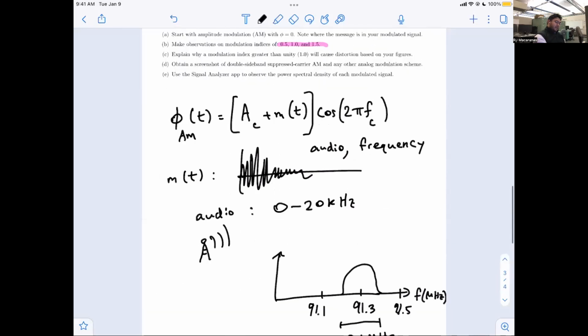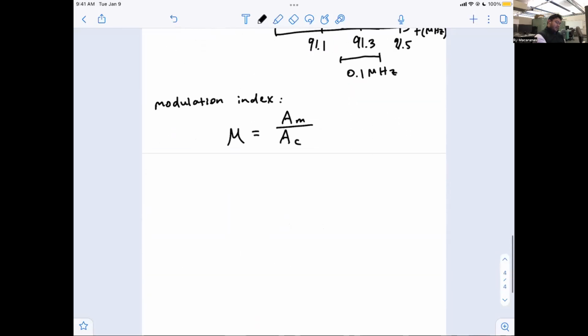So we usually have this carrier frequency. First off, the carrier frequency is usually much greater than the message frequency. So that's one assumption that we have when we make this amplitude modulated signal. And ideally, we want our carrier amplitude to be greater than the message amplitude. And that's just so that when we carry it up, we don't observe this folding effect.